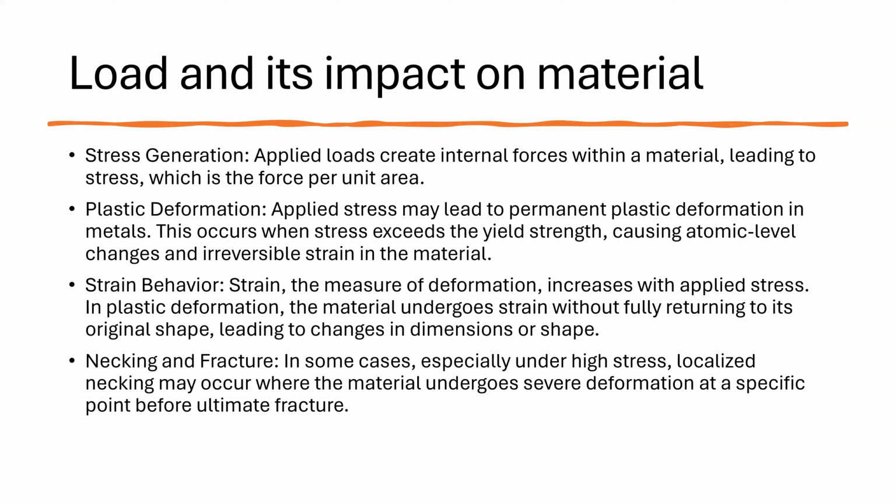In plastic deformation, the material undergoes strain without fully returning to its original shape, leading to changes in dimension or shape. Necking and fracture. In some cases, especially under high stress, localized necking may occur where the material undergoes severe deformation at a specific point before ultimate fracture.